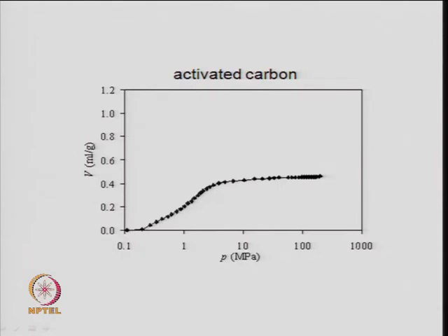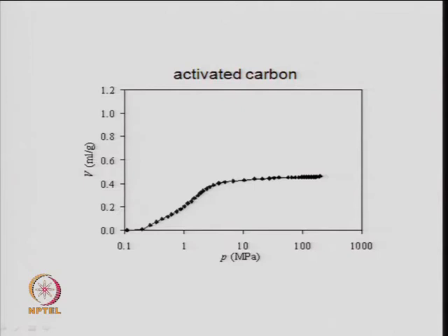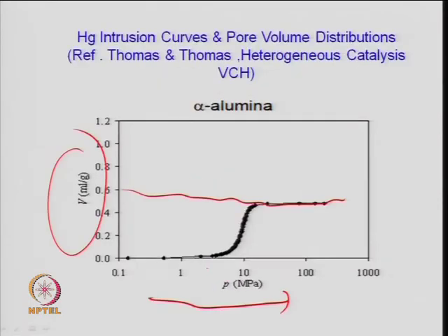Similarly, this is the curve for activated carbon. So, you can see that depending upon the type of the sample and their pore size, you have different kinds of behavior here. Here the pressure is smaller, because it may be a wider pore, right. So, the pressure requirement is smaller to fill all the pores here. If you look at 9 or 10 MPa, all the pores are filled, whereas in this case,